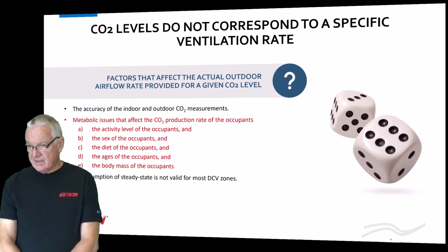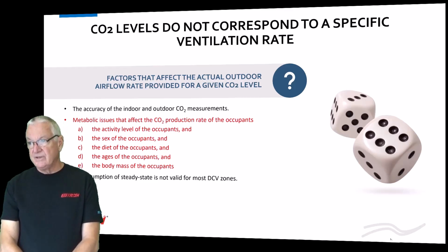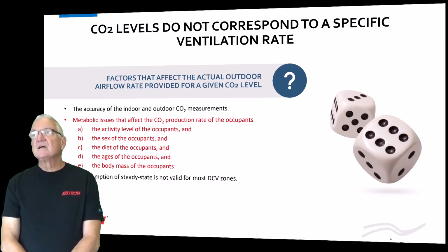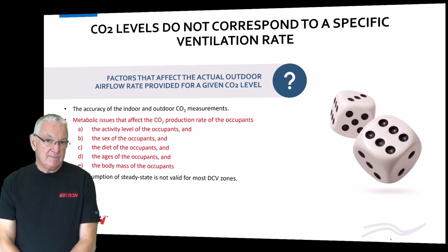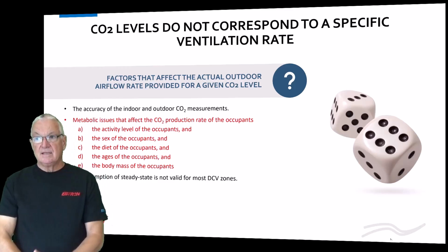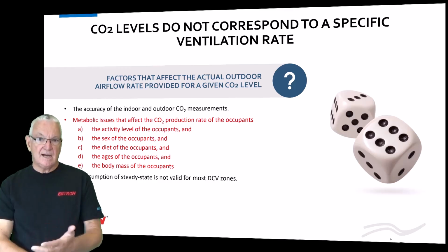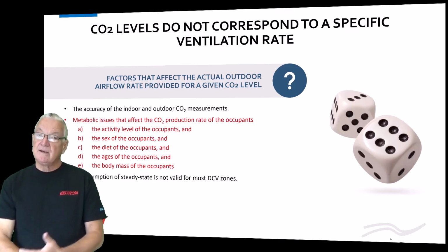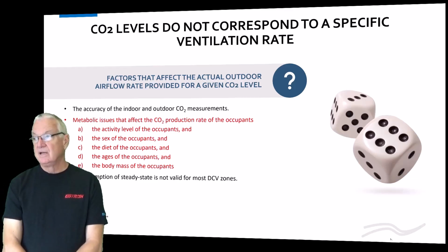And then it got modified again and didn't get approved. And then finally, to make it easy, they made some table values that you can go back and modify to get close to what the CO2 set point should be. But I'm afraid nobody's going to do it. They're just going to look at the CO2 levels in the table. And when they do, they're based on occupant default densities, and we're going to end up underventilating people, which I'm thinking was really the intention.